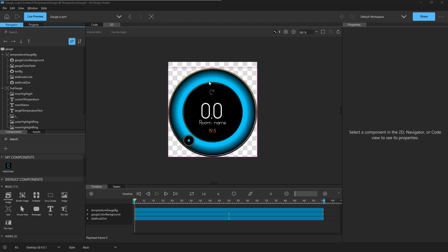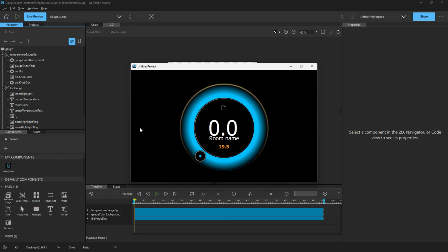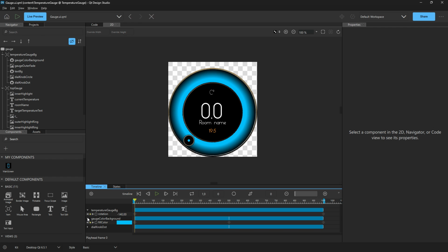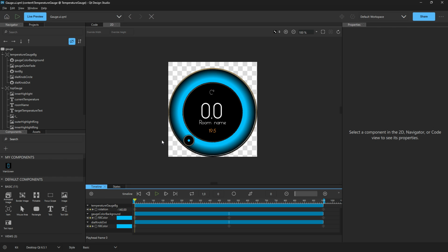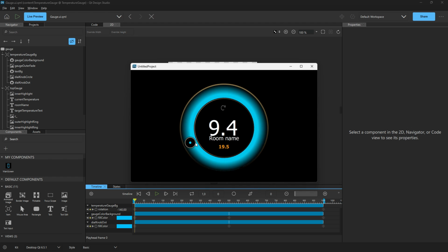First, let's run our example and see what has changed. I'm now able to select the temperature, and the background color changes when I set different temperatures. This has been achieved by one of the biggest benefits that Qt Design Studio provides in order to break the glass ceiling of other designer or asset creation tools. With the help of timeline animations and setting keyframes on the corresponding item properties, our dial is now able to rotate for the selection, and the background and dot of our knob are changing their color after we attach keyframes to their fill color property.